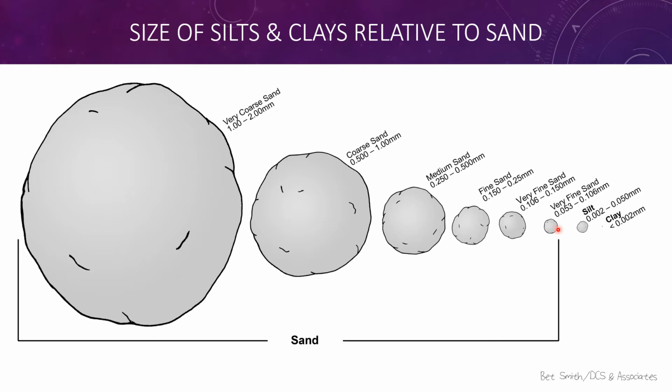There are some that say that that's also silt because sand really starts at 74 microns. And then from 2 to 50 microns is definitely silt in anybody's book. I use 2 to 74 microns. And then clay starts to be those solids that are less than 2 microns. I usually use the 0.5 micron to 5 micron range for the clay.